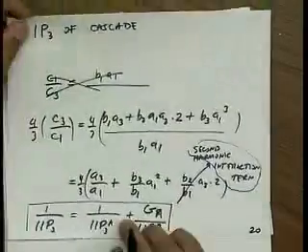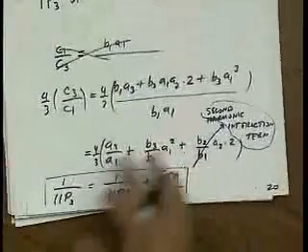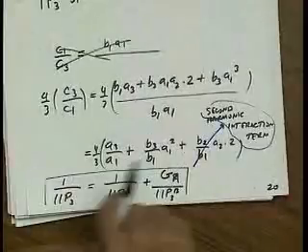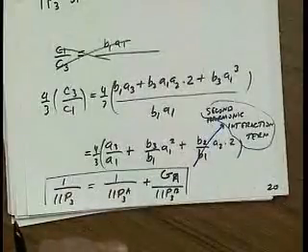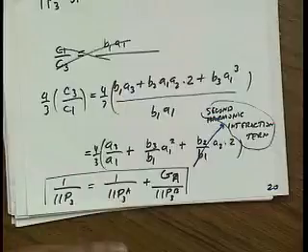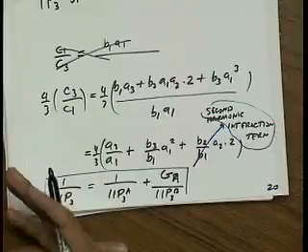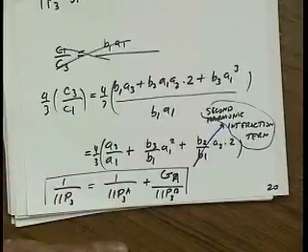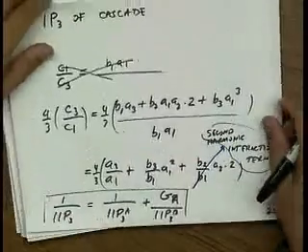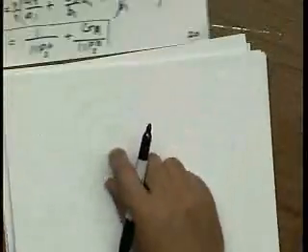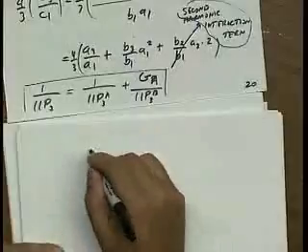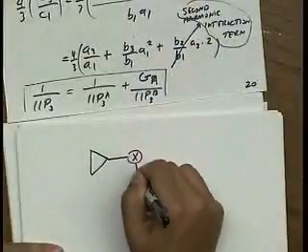Okay, so coming back to this input IP3, the exact same calculation that we did for IP2 also applies to IP3. Usually you get into situations where the IP3 of one device will dominate. So for instance, if I have an LNA and a mixer, we haven't talked about mixers yet, but a very common combination is an LNA driving a mixer.